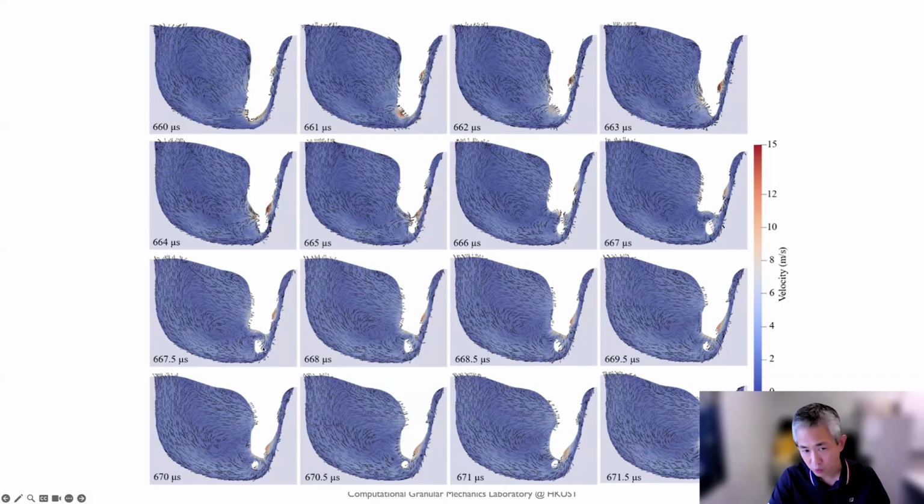This bottom part will become closed in and leave inside of this metal pool liquid here. And this metal pool, you imagine there'll be a velocity moved backwards, and this will carry this pore and move behind here. And during the process, it can really develop condensation such that its volume will shrink. So the volume will shrink and become smaller.